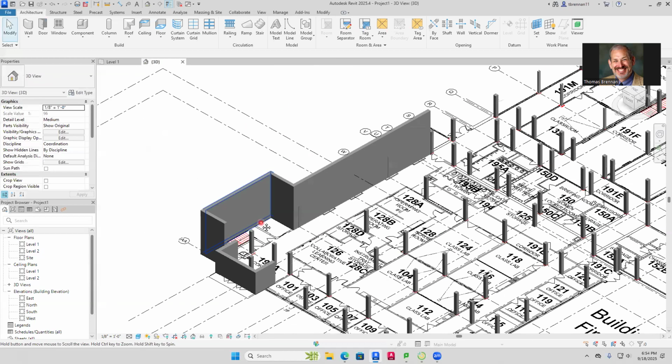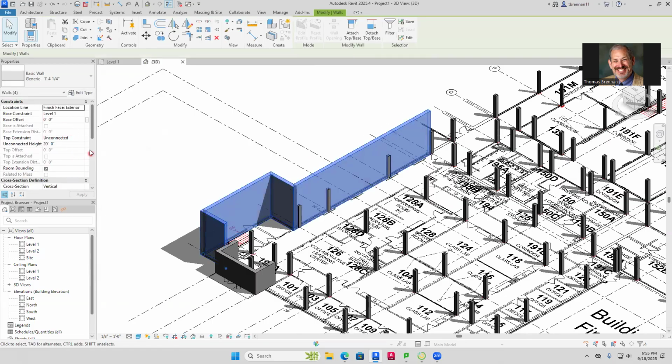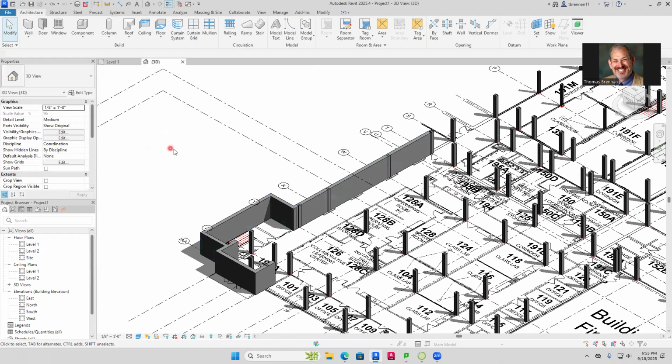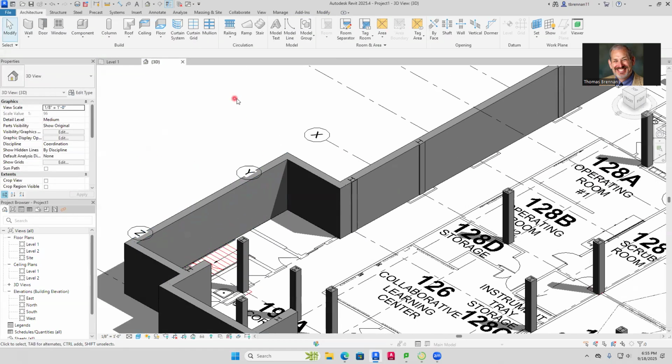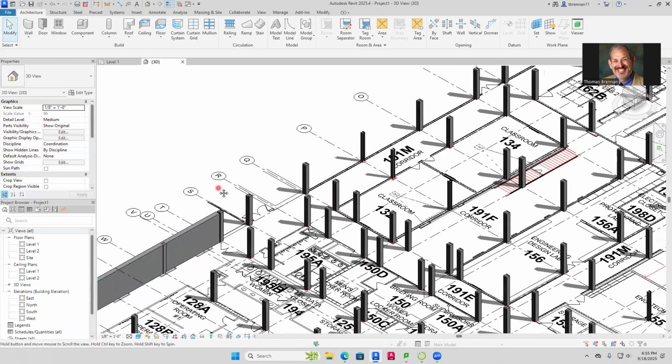And you do this. Now, notice what you got here. These walls are also too tall, so I'm going to highlight them and change those too. One thing you can do as you're going along, as you're drawing these, is start and do that step first and just make it up to level 2, and that'll save you having to do this each time.